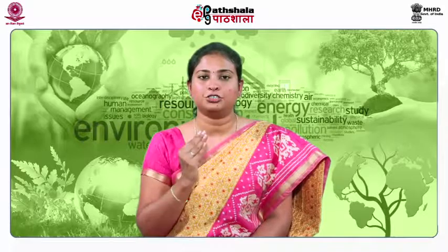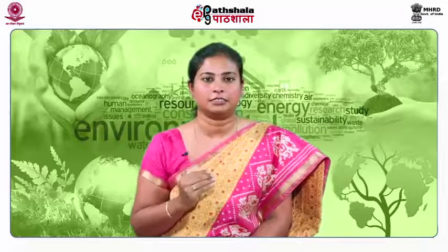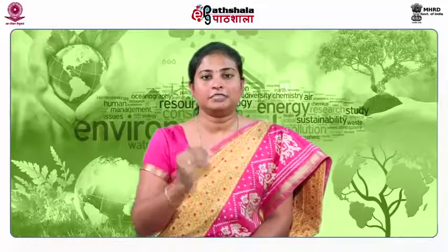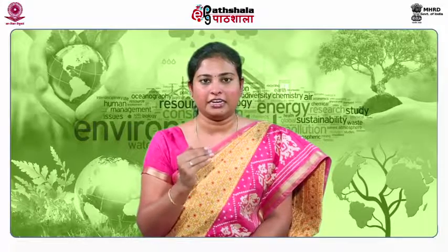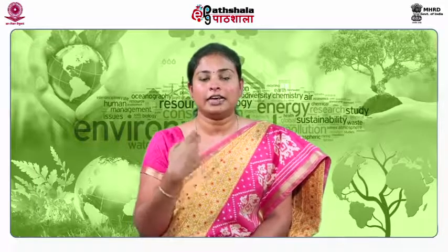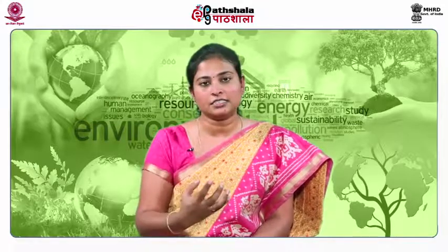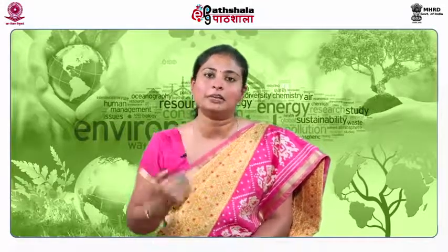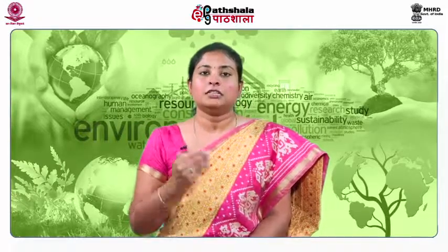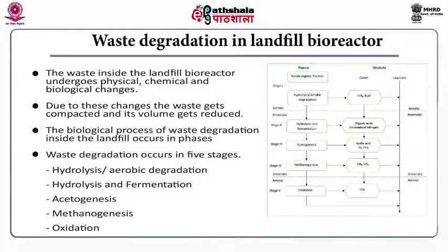The landfill bioreactor should be continuously monitored, which gives the significance of an environmental monitoring system. This component helps in assessing leachate or gas leakage, if any, during environmental contamination. That means if you continuously monitor for gas leakage, or continuously assess the leachate characteristics, you can judge what process is happening inside the landfill bioreactor. The last one is closure and post closure monitoring. Let us look into the various processes that take place during waste degradation within a landfill bioreactor.